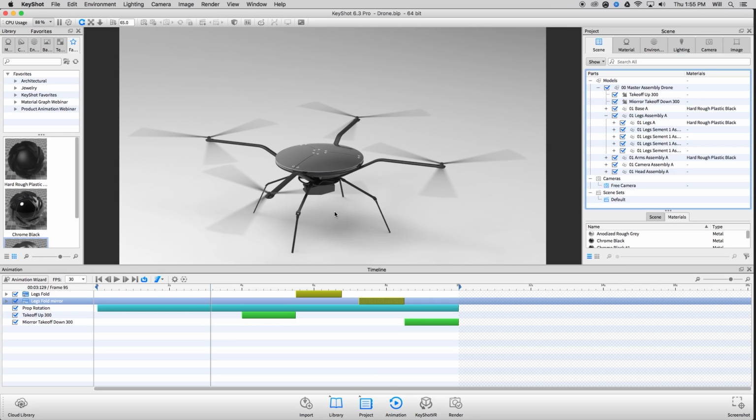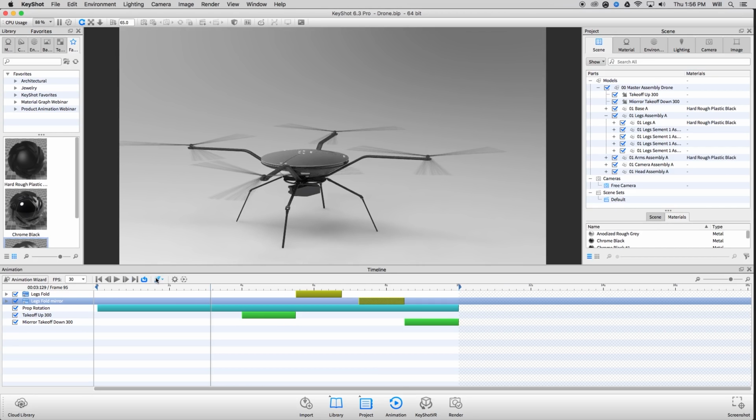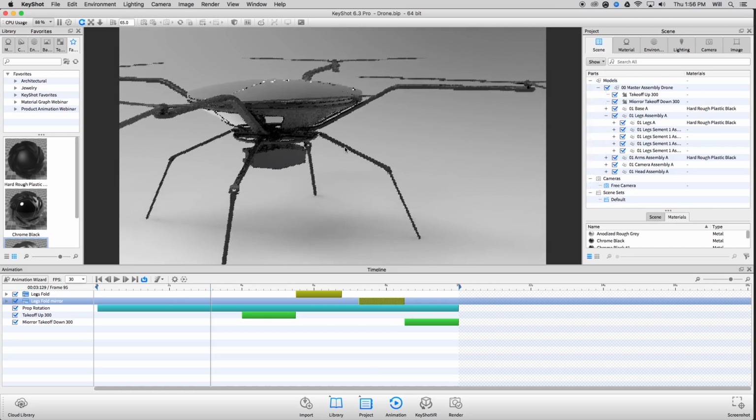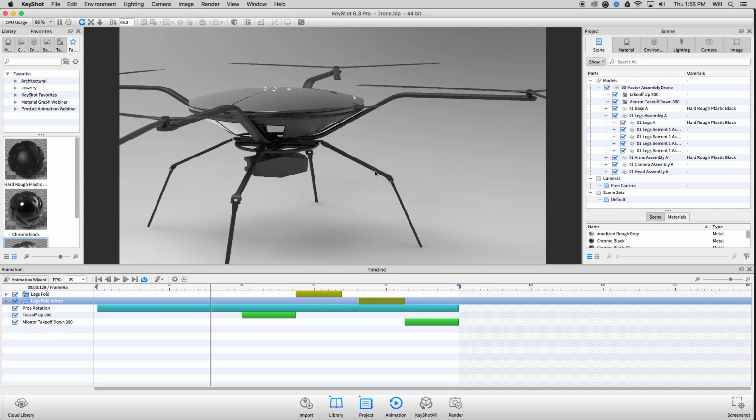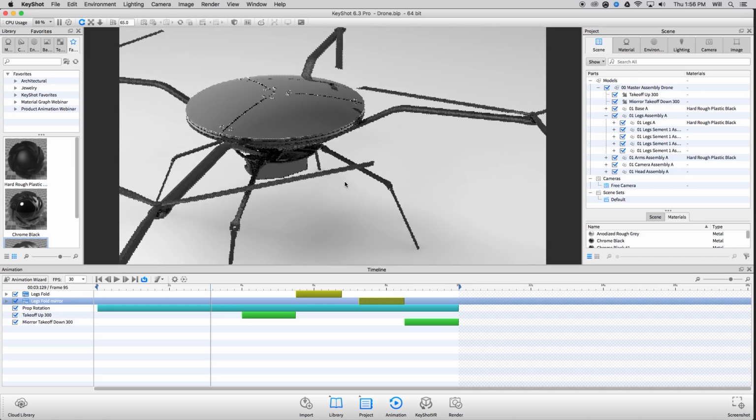Got it. Okay, that's a great question. So for those who are using Rhino and are unable to take advantage of local axes that, say, a CAD user might be able to, we do have some workarounds in KeyShot. They may not be quite as elegant, but there's two options. First and foremost, if you want to use a piece of geometry that your model already contains as a pivot, we can do that, and it will essentially look at the center of that piece of geometry.